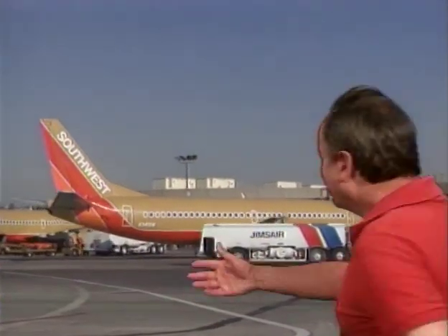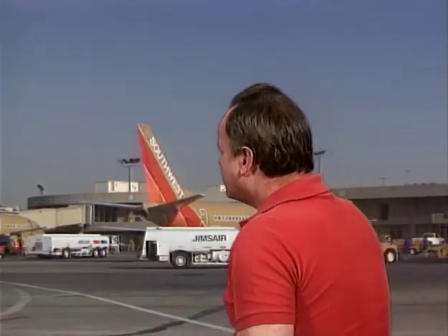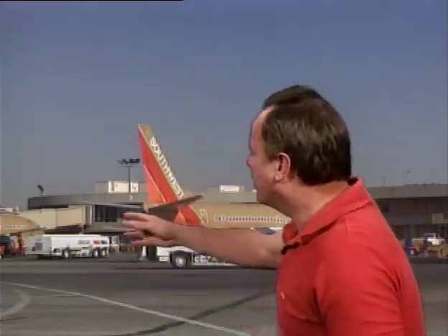You know, when an airliner like this Boeing 737 gets done with a trip, it's going to taxi into the gate and park for a while while they unload passengers and put on new passengers and clean the aircraft and so on. And during that time period, you would still like to have the aircraft air conditioned. So you need bleed air for that. You're going to need bleed air to restart the main engines. You need electrical power when you're doing that.